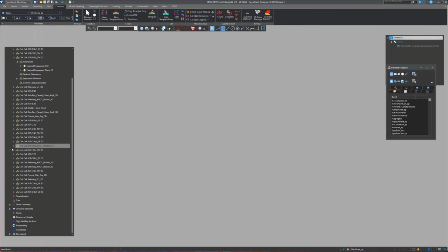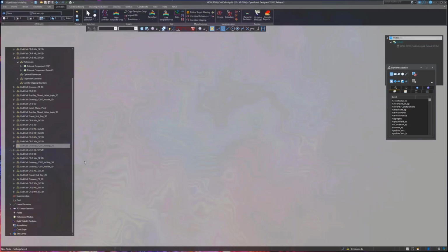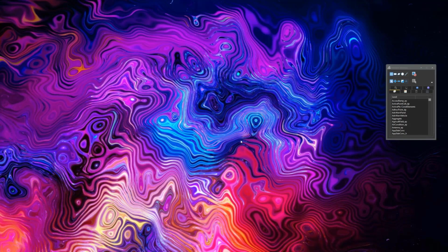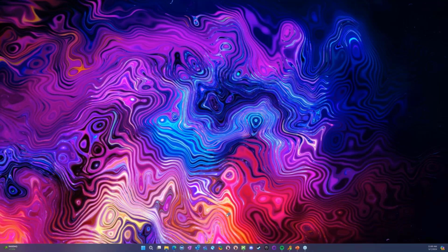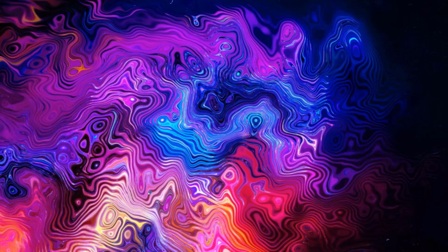Keep the original, and then you can start using your 2D civil cell line work to build your 3D civil cell. That's how I've been doing it. Always do the 2D first, and then work on the 3D, because then I've got all the 2D line work now, and I can move on to making the 3D stuff work.